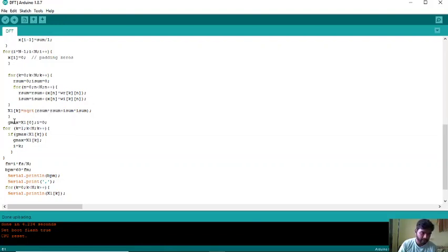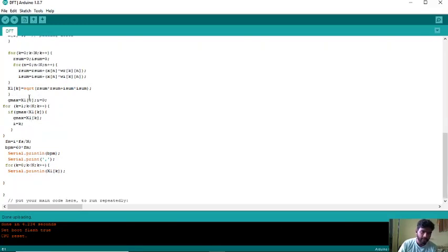And then once we get the X of k values, we'll find the dominant frequency index. That is, if there are a lot of frequencies, the dominant frequency means the frequency for which the magnitude of the spectrum is maximum, and we'll find the index of that frequency and store it in i, and then we'll find the BPM.